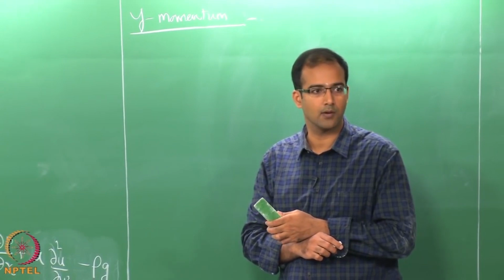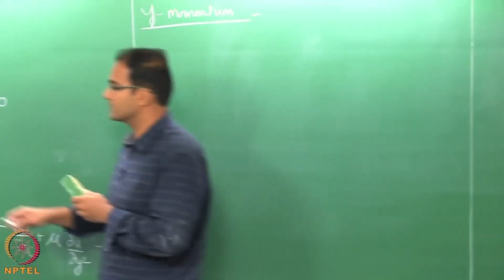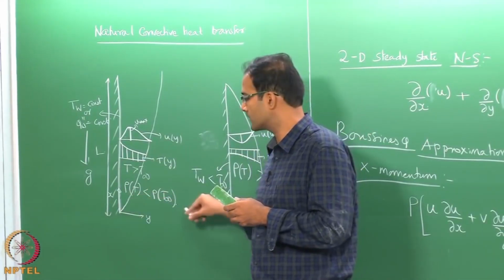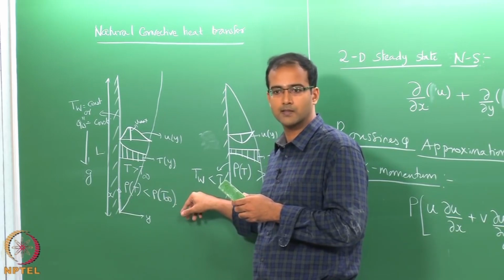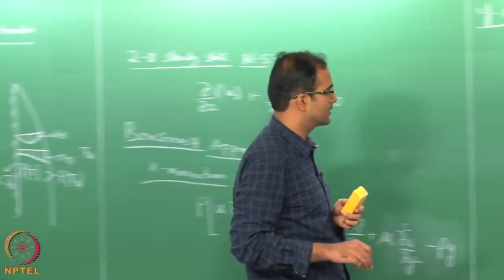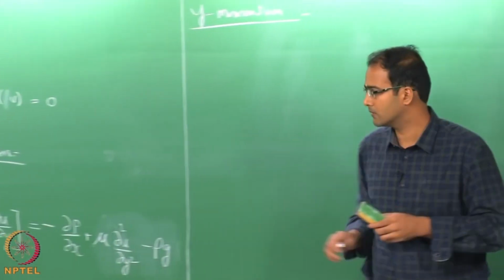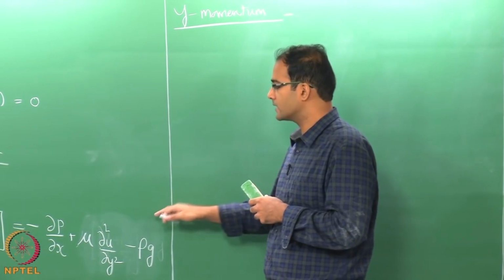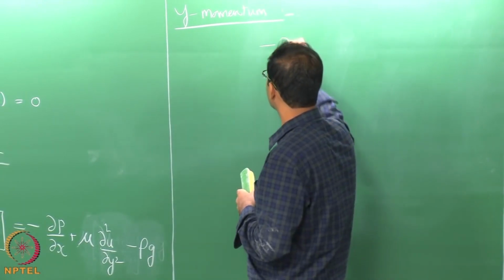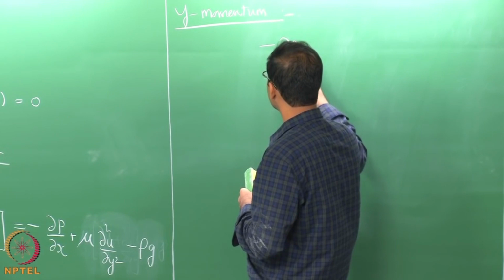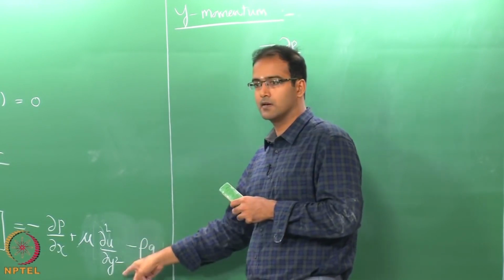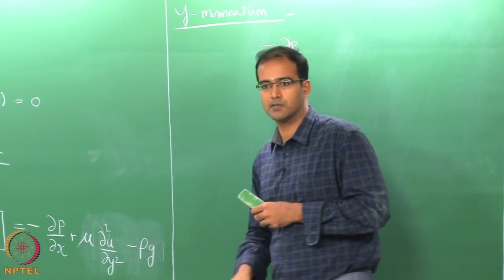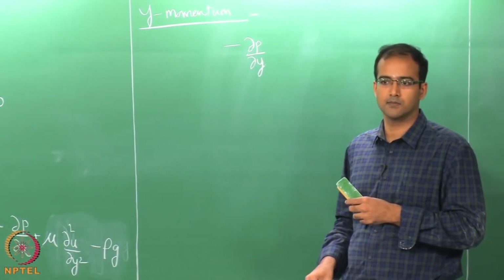In this case, we have only u velocity, which is varying as a function of y. We do not have any v velocity, that is velocity perpendicular to the plate length, okay. So, therefore, the convective term of the y momentum equation will be 0. On the right hand side, you will have the pressure gradient term dp by dy, there is no diffusion of the v momentum also, and there is no body force in the y direction, okay.